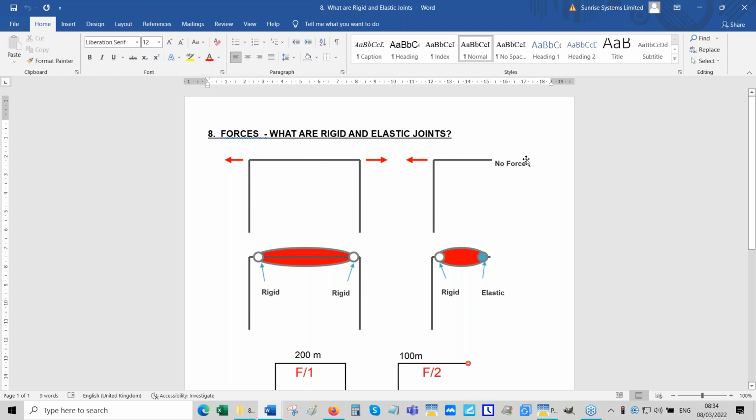There's no restraint or anything like that here. Then the unbalanced force is simply that component. There's nothing compensating or acting to balance the force in the other direction, because it's a free end of a pipe which is not restrained in any way.